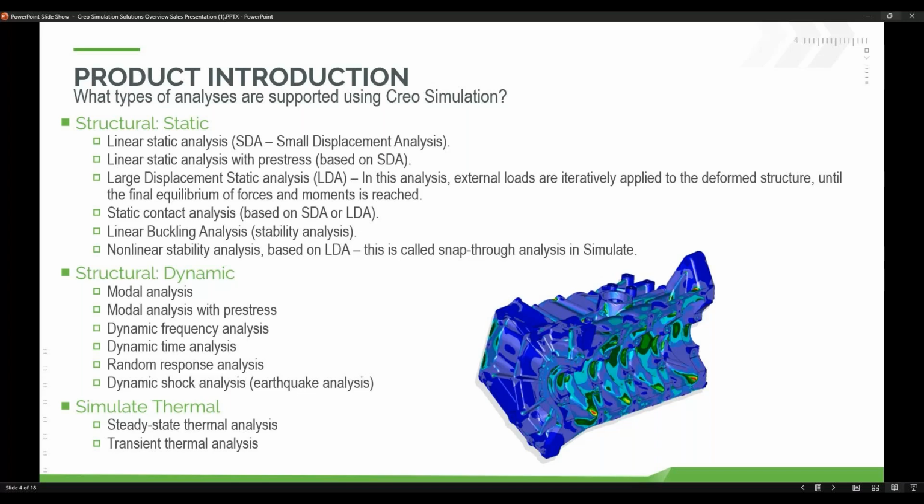We can do large displacement analysis. This is where you have external loads that cause the object to get deformed more than a slight bit. So let's say you've got a diving board. The diving board is going to flex for many inches, if not a foot or two at the end of it, as you're bouncing on it to get into the water. That deflection is a larger amount than the diving board is thick. So it would be a large displacement over a small area. So that would be considered a large displacement analysis.